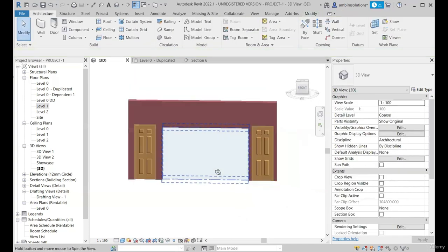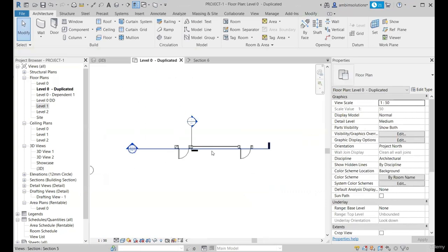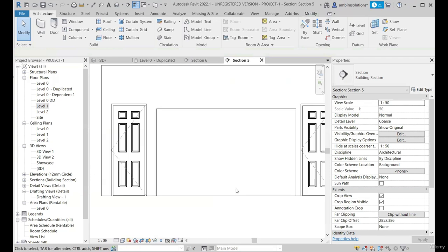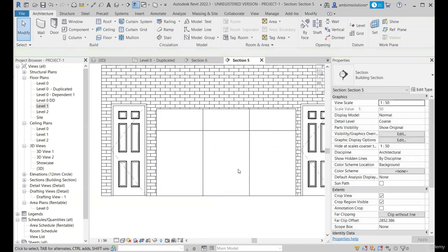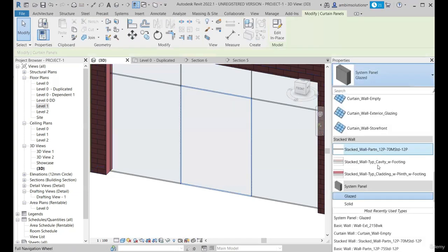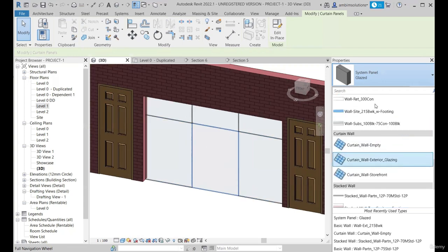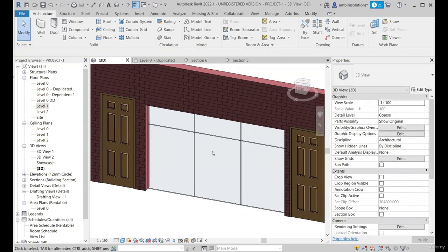So in order to place a door or any glass partition for a curtain wall, you first need to set the grid lines. I'll quickly show you, as you have seen the grid lines in the last lecture. I've just created a grid in this fashion. I'll keep this center part open, as a door would be fit here. Let's go to the drop down panel, and we can see there is no door actually present. As we have replaced the panel system, like the glazed or solid, with any wall, similarly you can replace this panel with any door or window system. Let's check an example for it.